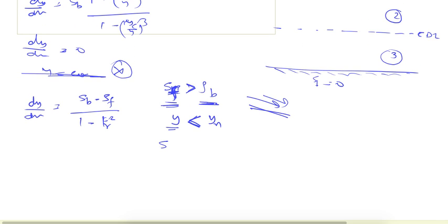And if it is less than bed slope, it means that bed slope corresponds to the uniform flow depth. So if the friction slope is less than the bed slope, it means it is something flatter. For the normal bed slope it is something like this, and now I'm making it flatter. So if the slope is flatter, the flow will retard, so the flow depth will be more.